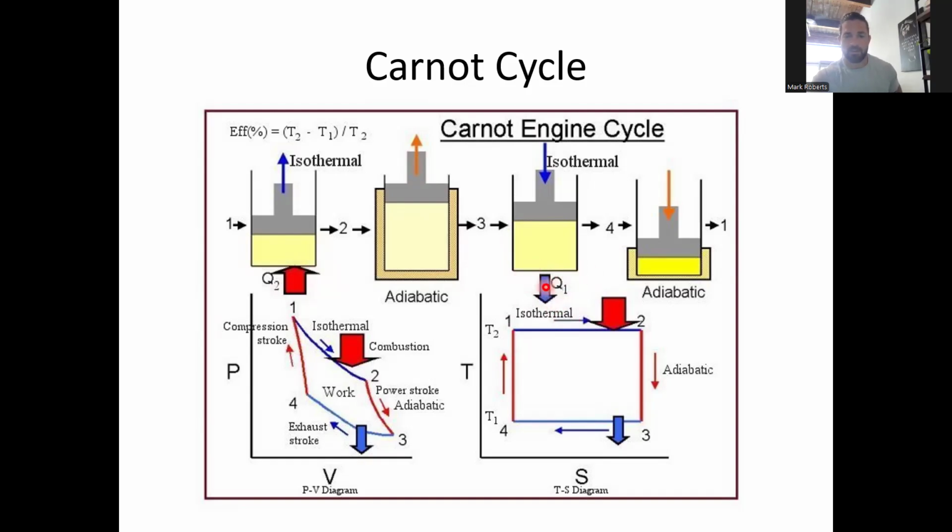And when we put this in contact with the ambient temperature, the system will compress as the gas is cooled and rejects energy to the environment. And then again, once we remove that, the pressure inside the system is lower than the pressure on the outside. So the piston will continue to compress until it reaches the same temperature and pressure.